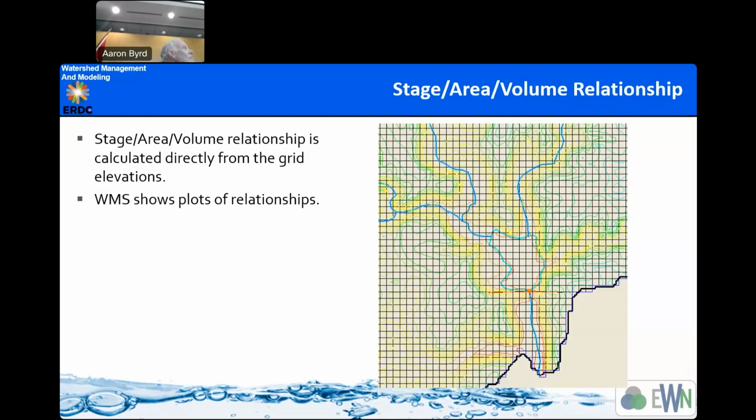So with all the different options, have you tried to do pumping scenarios within GSSHA? Let's say you had a detention pond and you want to pump water out of it to another location. Yeah, we've done studies. You can pump from anywhere to anywhere, from the overland, the stream, or the groundwater. You can pull it out. You can put in a negative or a positive. So you pull out of the stream and put it on the overland flow, or pull out of the stream and put it in the groundwater. Whatever.